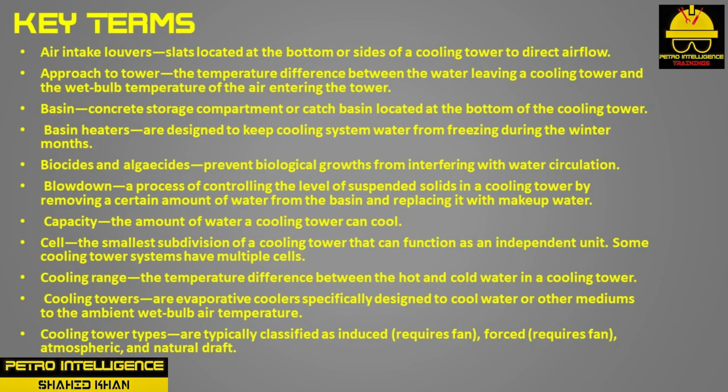Basin heaters are designed to keep cooling system water from freezing during the winter months. Biocides and algicides prevent biological growths from interfering with water circulation. Blowdown is a process of controlling the level of suspended solids in a cooling tower by removing a certain amount of water from the basin and replacing it with makeup water. Capacity is the amount of water a cooling tower can cool.